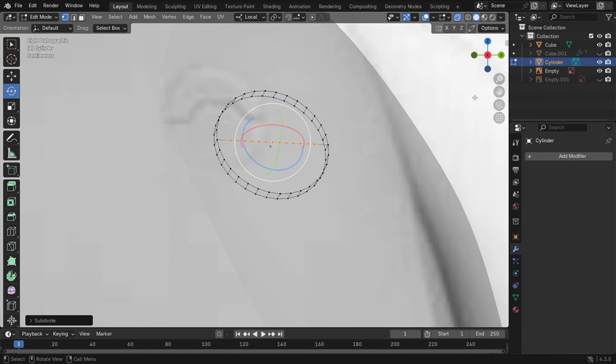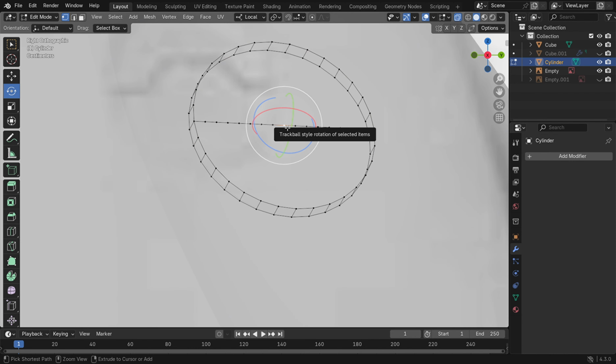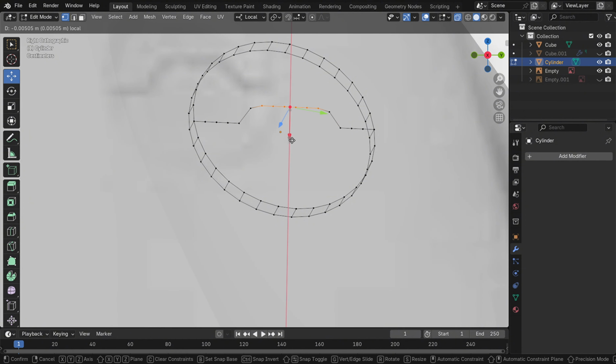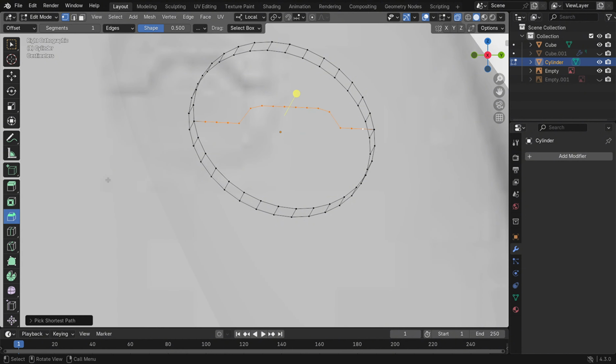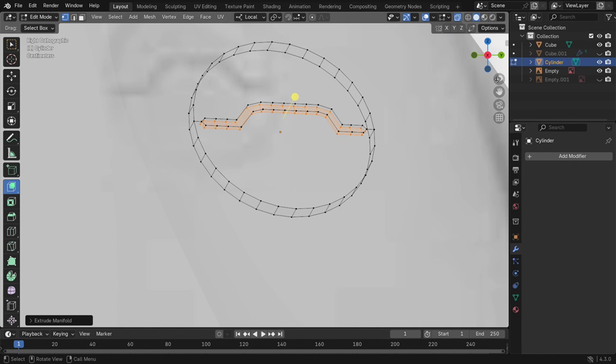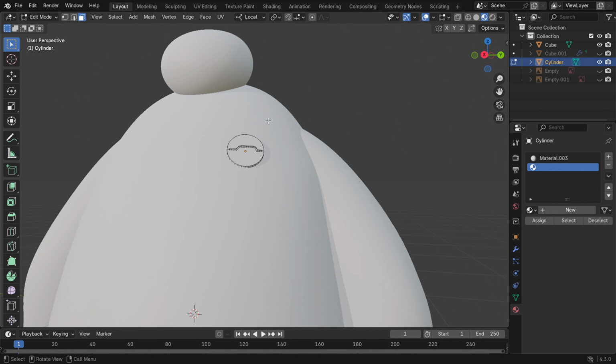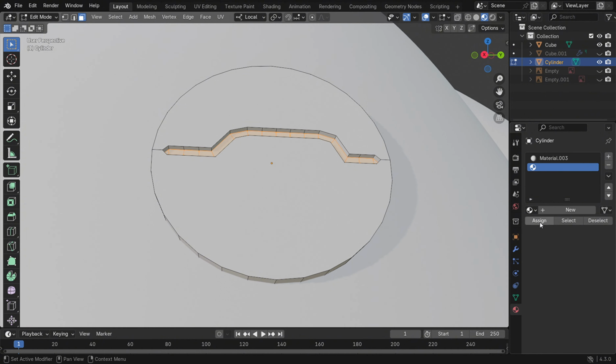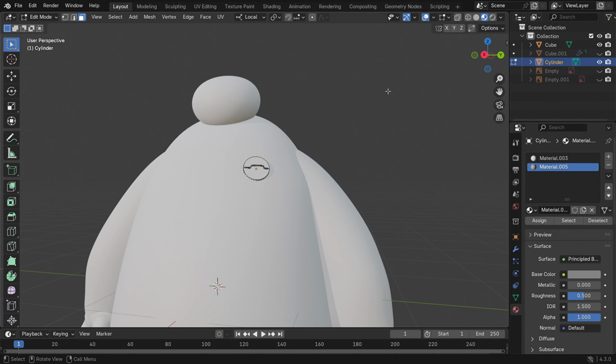Use the knife tool to create a cut in the middle, and subdivide this cut, selecting the central parts to lift them upwards. By applying the bevel operation and extruding inwards with the manifold option, we'll create the desired indentation.